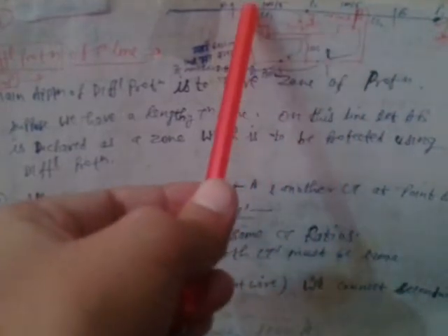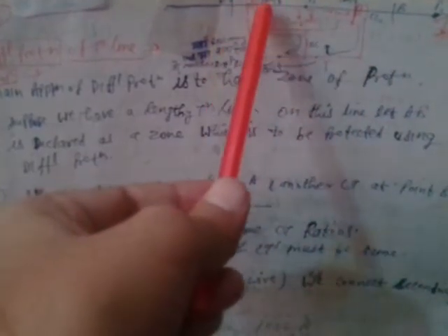So as per the CT ratio, CT1 secondary current will be 50 ampere and CT2 secondary current will again be 50 ampere, right? Both the CTs are seeing the same fault current. So the operating coil current is 50 minus 50, that is 0 ampere, right?